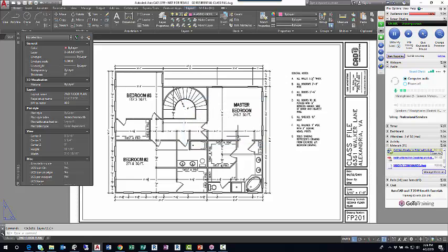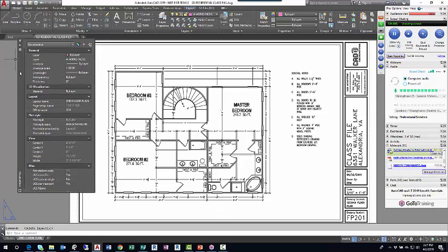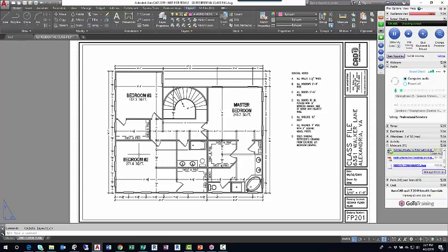Say OK. Sometimes when you're plotting and AutoCAD sees that I have 2 or 4 or 6 drawings open, or one drawing that has multiple layouts, when I go to click print or plot, and I think I've disabled this dialog box, but you might see it on your computer, AutoCAD will say, I see you have multiple layouts, do you want to batch plot them or whatever? It's not a big deal. It's just kind of a speed bump, and I just want to avoid that. So I'll dismiss this, and with that name change, second floor plan, I'll save the drawing.